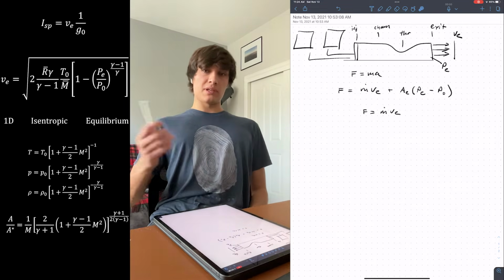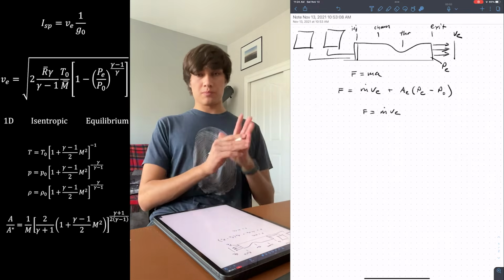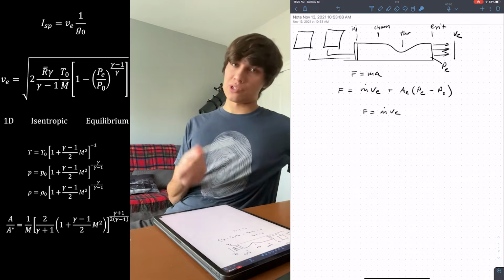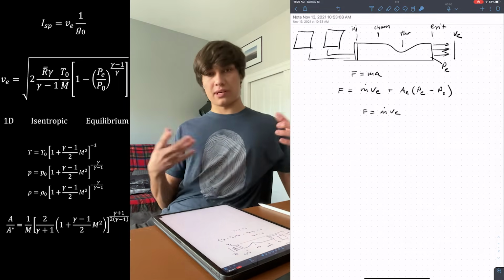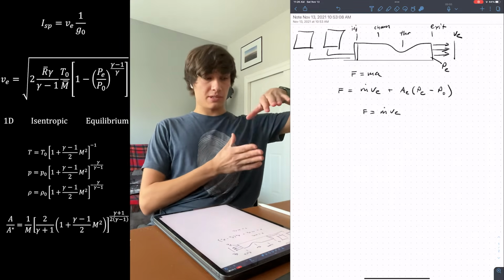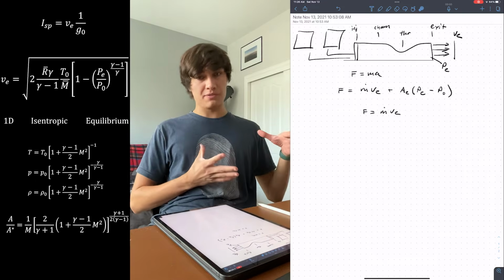The second part of the argument is going back to when we said that the flow only varies with station inside the rocket engine. We can then make the Mach number a function of the cross-sectional area using flow continuity for the isentropic process. So that means, as in the subsonic regime, as the cross-section decreases, the flow speeds up. In the supersonic regime, as the cross-section increases, the flow speeds up.